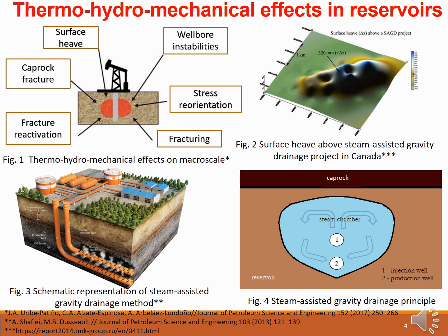of heavy oil recovery. According to this method, a number of horizontal wells are drilled one above the other, as illustrated in Figure 3. The upper wells are used for the injection of the hot steam, while the lower wells are used for the oil accumulation.